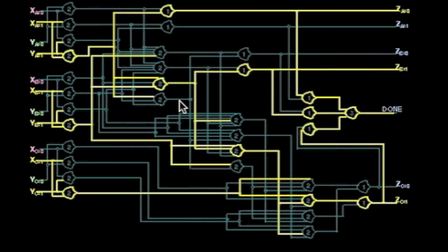So as the data flowed through the circuit, only correct transitions to data occurred. So when the outputs become data, we know that that's the correct resolution of the presented input. And we can detect when the output becomes data, it transitions from null, and we can confidently generate our done signal.